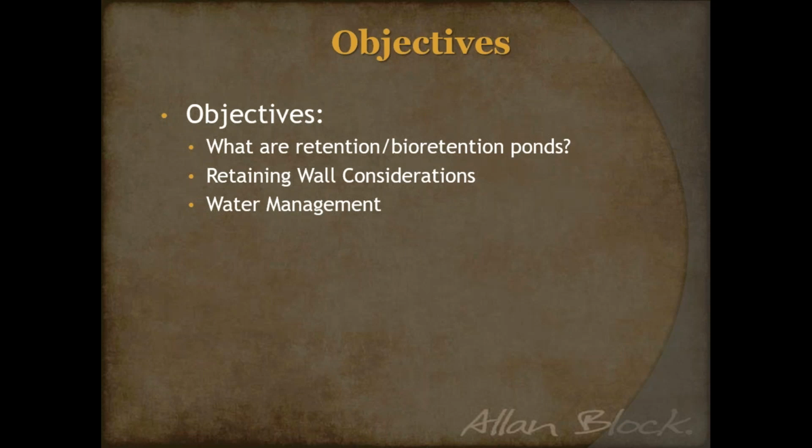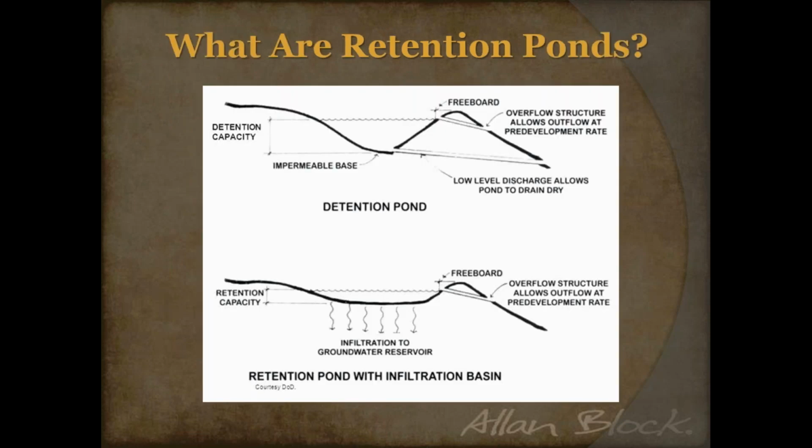So to get started, I want to just kind of define and highlight what the difference between a detention basin or detention pond and a retention pond is. And it's kind of in the name. I've always kind of referred to them as detention ponds. You're kind of detaining the water. So you're just temporarily holding it before it's discharged. And that discharge is always through kind of a single point source or through a pipe. So like you're capturing that extra capacity of water, but it's still being discharged in one location.